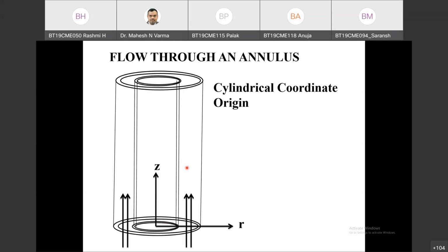Roll number 2, Abhishek. Yes, sir. Why it will be not at center? Because we have two forces at the two sides. Because it is not a symmetric velocity profile. But you told about forces also, no? Yes, sir. This maximum velocity front will depend upon the drag force exerted by this surface and the drag force exerted by this surface. So where it will be, near towards this wall or near towards this wall?